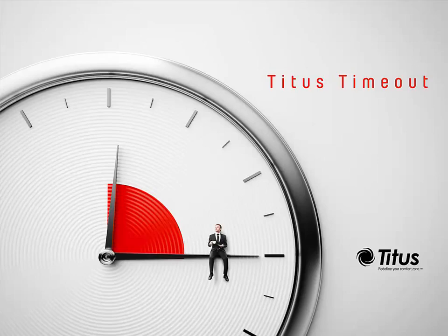I'm Jenny Abney-Civey, and I've spent the last couple weeks discussing air change rates, laminar flow, air curtains, and some other things. So now we have all the pieces that we need to discuss air distribution requirements of ASHRAE Standard 170, ventilation of healthcare facilities. ASHRAE 170 defines the ventilation system design requirements for patient care areas and related support areas of healthcare facilities. This includes hospitals, nursing facilities, and outpatient facilities. It covers new buildings and additions to existing buildings.